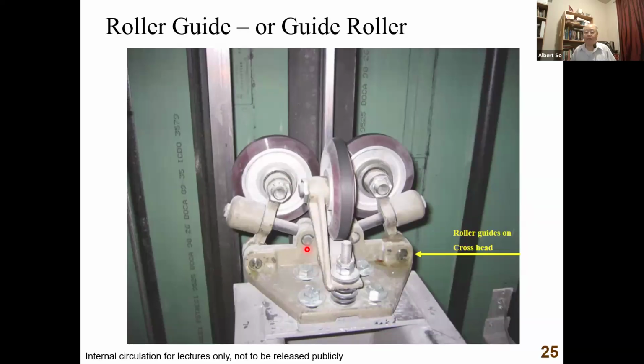Okay. One question: landing door will close earlier than car door, and car door opens earlier than landing doors? No, they open at the same time. I told you before. There's no power to the landing doors, so the landing doors cannot be opened and closed automatically.